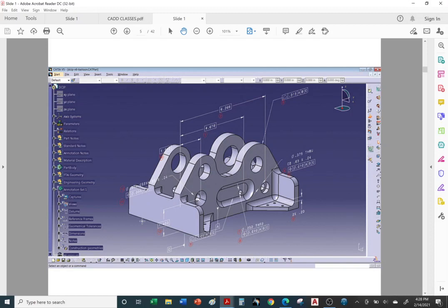So when a Northrop or a Boeing offloads the work to a machine shop, the machine shop says, hey, what's this length? Well, measure it from the 3D model. Just use your calipers or your measuring tool here, and it'll give you the length. Let's say it's 5 inches in length. Well, how much can I be off by? Well, typically in the statement of work, part of the contract on a document, or somewhere in a hidden field here with general notes, it would say, hey, anything that's not dimensioned, use a tolerance of plus or minus 30 thousandths. Okay, that's 0.030 inches.